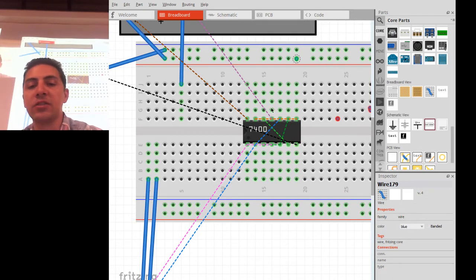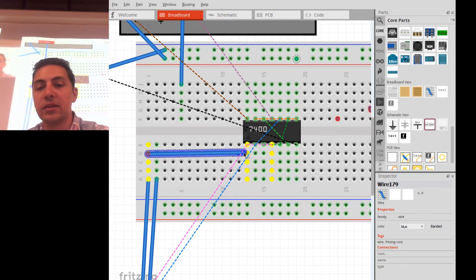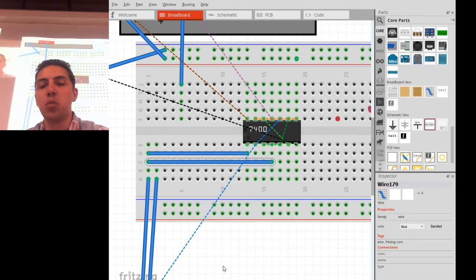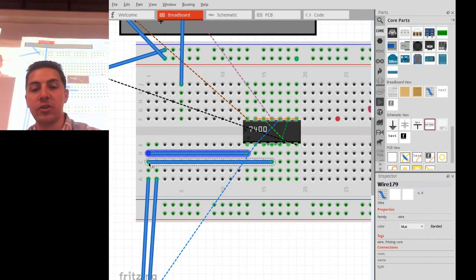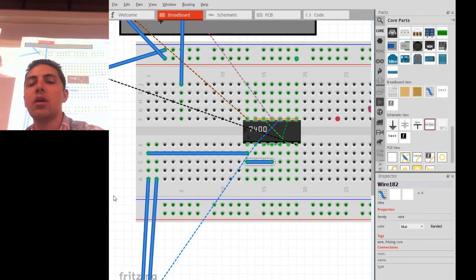So now I'm going to start wiring, and it doesn't really matter in what order you start because you're going to be moving wires as part of this pre-visualization process. So I'm going to just start with the inputs, and I notice right away that I need to connect up X there. And I also need to connect up X here. Now this is one way to do this. You can connect up from the source X to two different places. It does use up more wire though. A better solution is to daisy chain. So you go into this pin, then out of the next one over and off to the next.